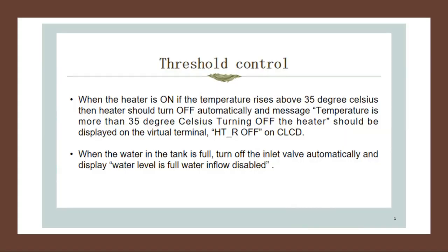Threshold control. When the heater is on, if the temperature rises above 35 degrees Celsius, the heater should turn off automatically and the message "Temperature is more than 35 degrees Celsius, turning off the heater" should be displayed on the virtual terminal and HTR off on the CLCD. When the water in the tank is full, turn off the inlet valve automatically and display "Water level is full, inflow disabled". The threshold controller is an important part in IoT as it makes the device user friendly and the user does not need to always check on the level of the temperature or the level of the water.